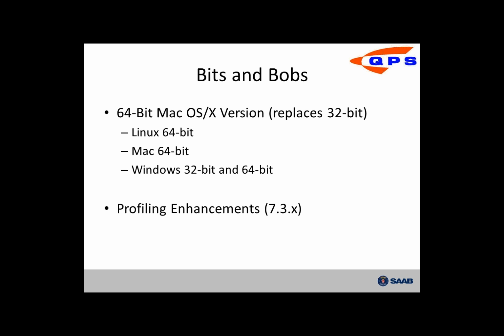Also wanted to highlight something you may have missed. We didn't do a webinar for a little while, so there were a number of profiling enhancements throughout some of the 7.3.x releases of the software. Greatly enhancing what we could do with the profiling. You can create a profile object, do cross profiles dynamically in your scene, as well as do multi-point profiling and dynamically adjust those profiles on the fly directly in the Fledermaus scene. So there are some great enhancements there that you may have missed. It's worth checking those out and seeing if they're useful for you.